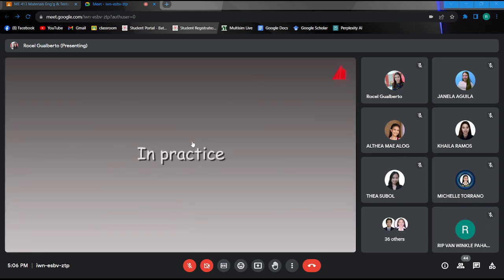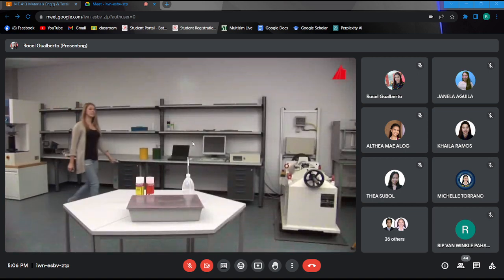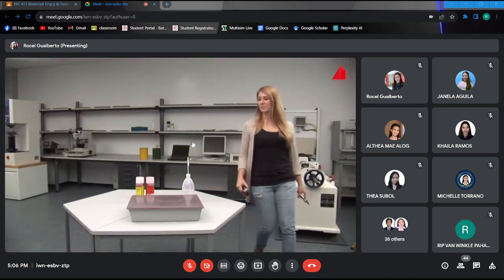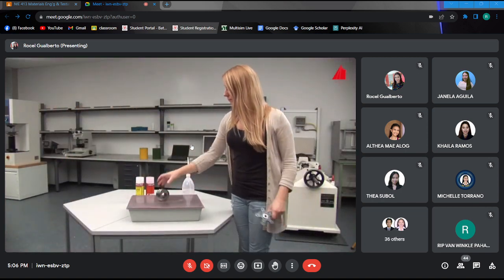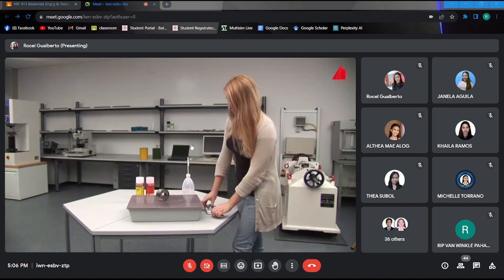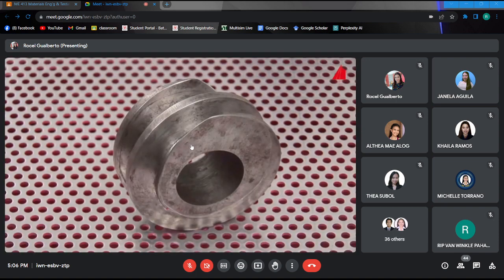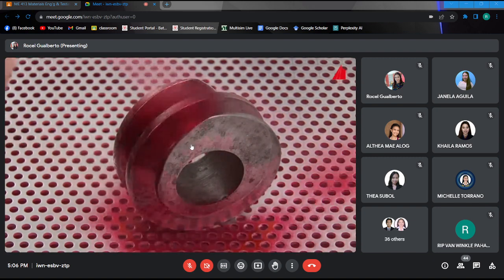And this is how it is carried out in practice. We wish to inspect two samples, a segment of a worm gear shaft and a broken bicycle crank arm. Both test pieces have already been cleaned. First in line is the worm gear shaft. The material tester applies the penetrant.